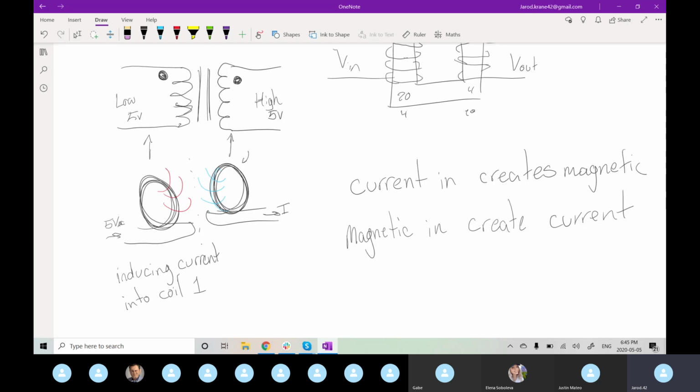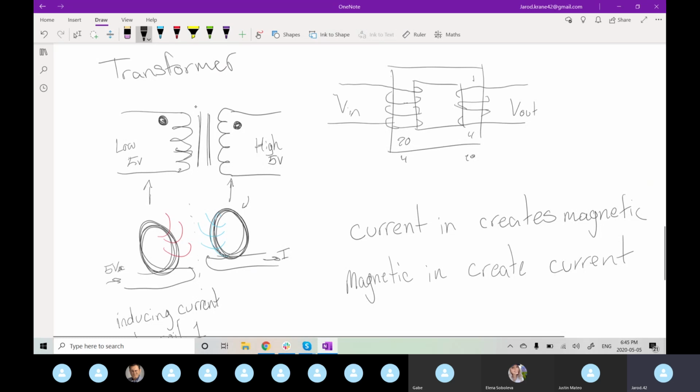They can be fully isolated from each other, so that one half of your system can be driving the low voltage portion of your circuit, while the second coil is able to run high voltage electronics that may be on the other side of your board, because you don't want to mix high voltage and low voltage in one plane. You don't want high voltage ground and low voltage ground to be connected, for various reasons.